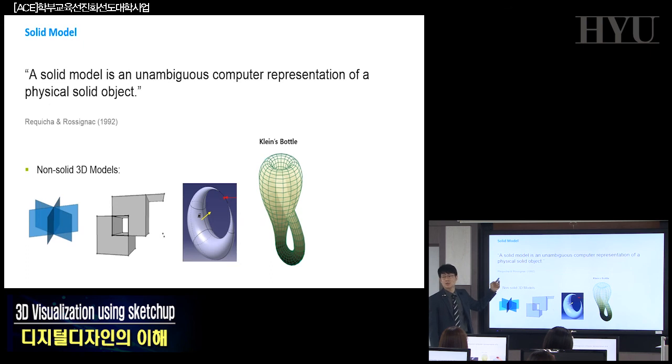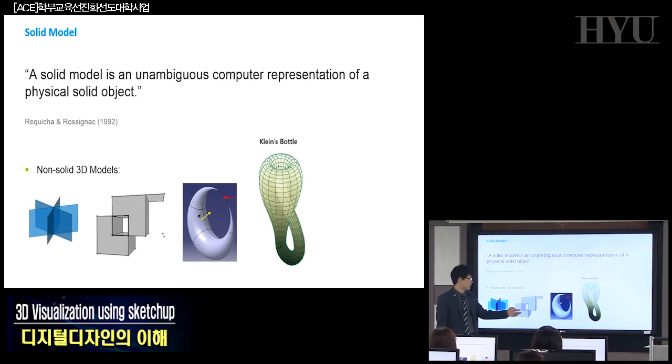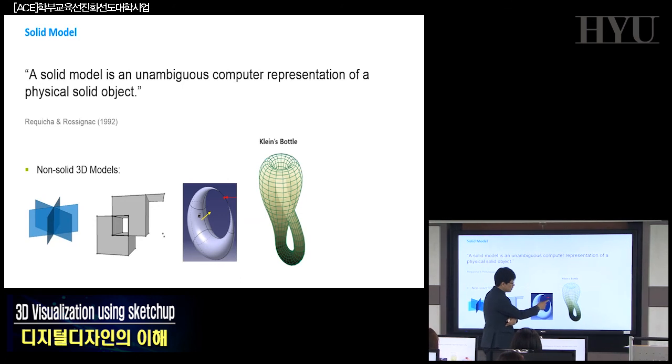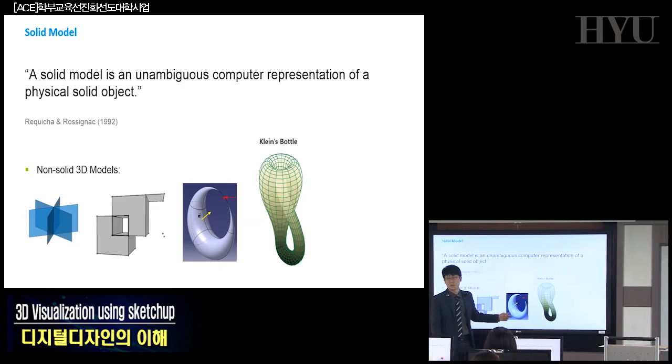It's mathematical, it's conceptual, nothing real. Even lines, curves, they are all mathematically defined or computer defined elements. But in the real world, there are no such points, lines, surfaces, okay? How about this? This one looks real. That looks fine. But take a look at this dangling object. This dangling surface shows this one is not a 3D solid model. In a solid model, there is no this kind of object. How about this? The string, this is a parametric modeler.